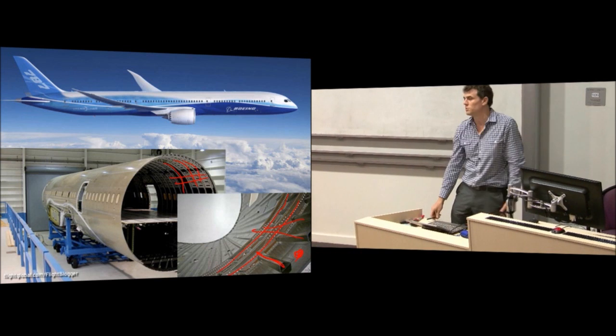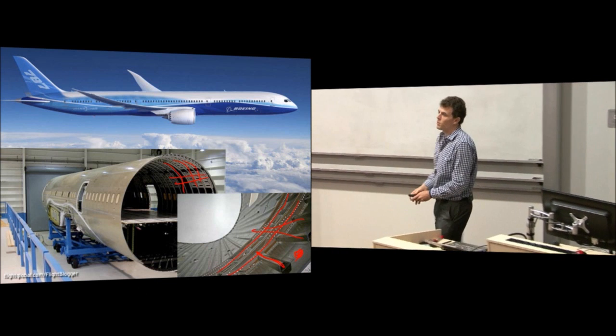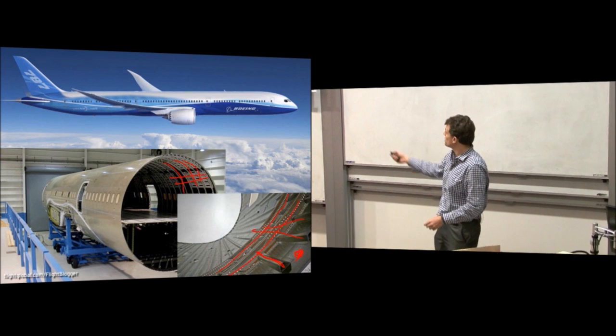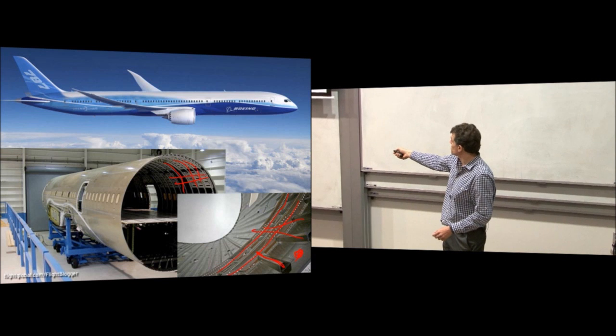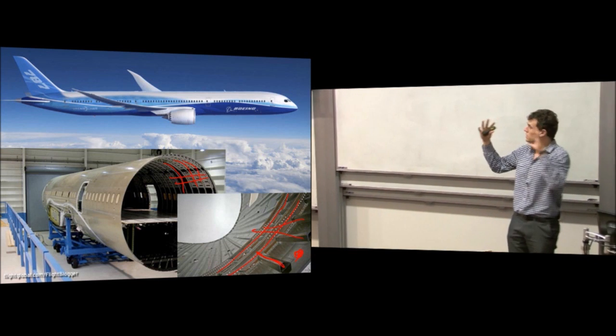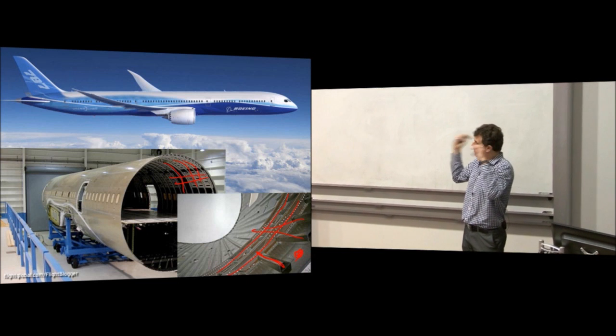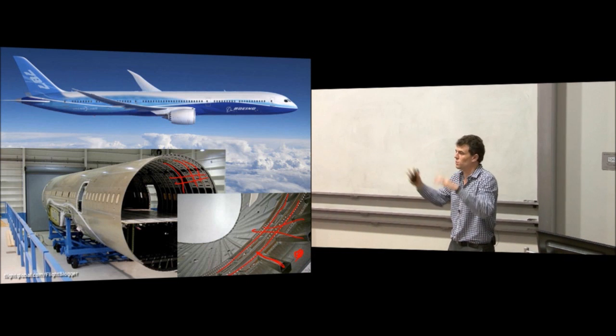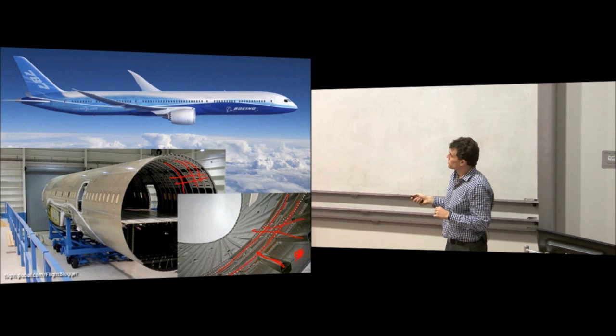But the whole thing is carbon fibre, and they make that in one big piece. The frames are bolted on, as you can see, there's fasteners here, but the stringers and the skin are made in one operation. They actually put the whole thing into a jig, pump resin into the whole thing, and cure it as one big part. And then they machine out all the holes.